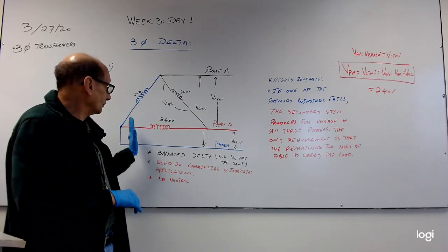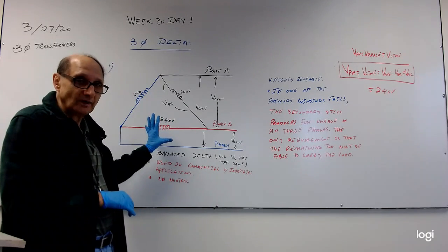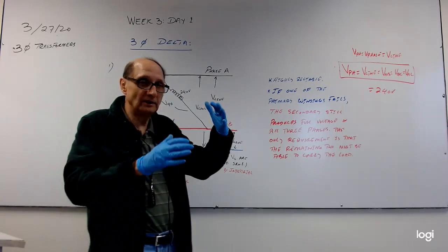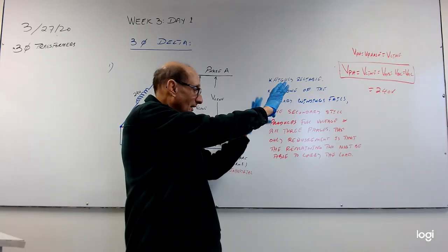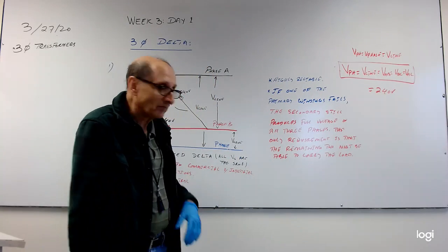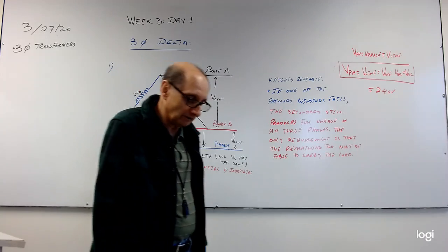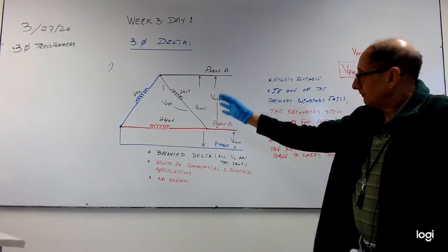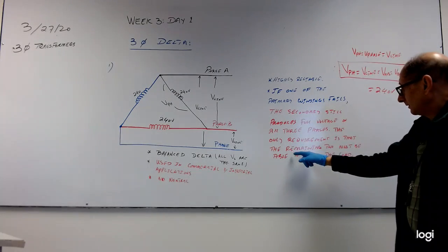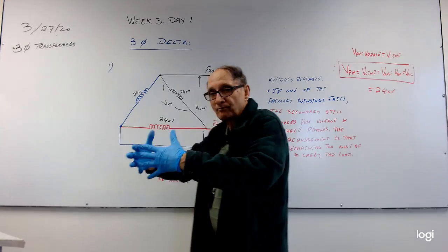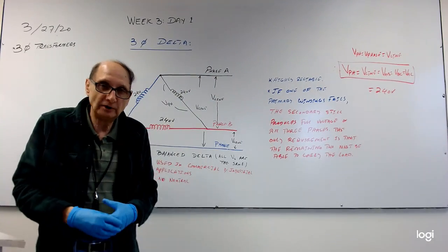So even if one of these windings, one of the coils, fails, we will still be able to produce voltage on all three windings on the secondary side. Okay, the only requirement is that the remaining two windings that are still intact should be able to drive the load.